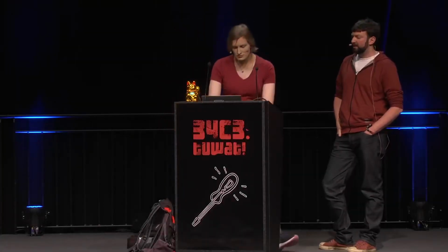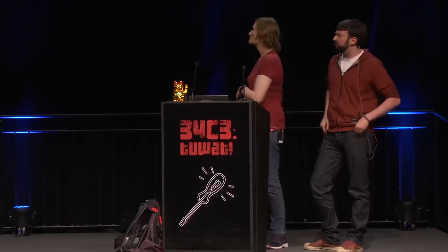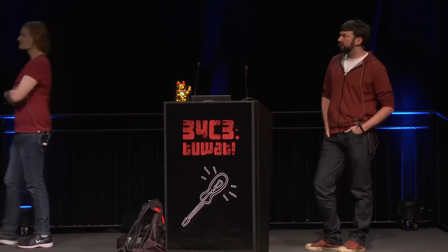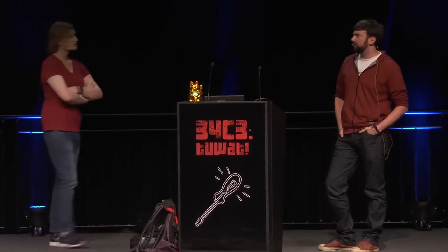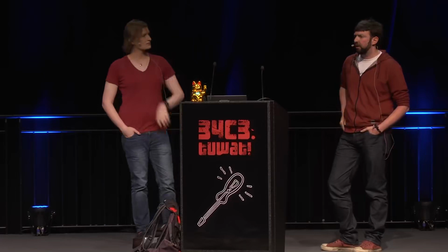back. And when it gets nothing back over the bus, it sort of says to memory, hey, I'd like to read this value. And the various peripherals, no one responds. And the DMA controller says, guess it's zeros then. And it just keeps going. And so if we can convince a DMA controller to read a section of RAM and just keep going, it will just read us zeros until it runs out, until its counter overflows.